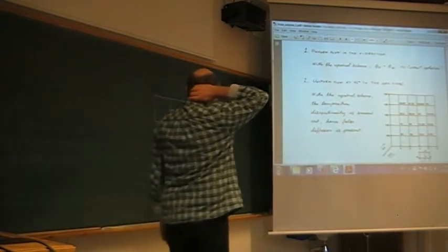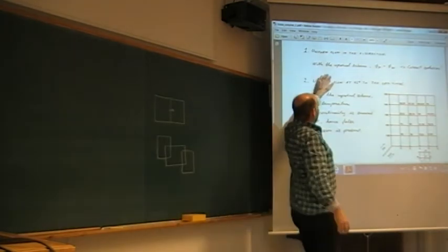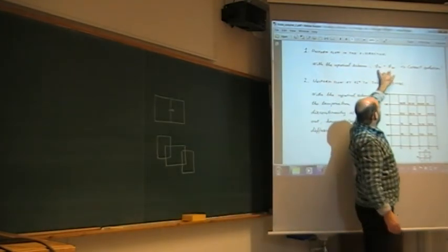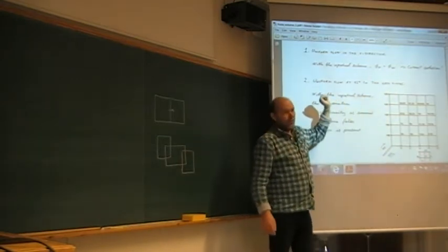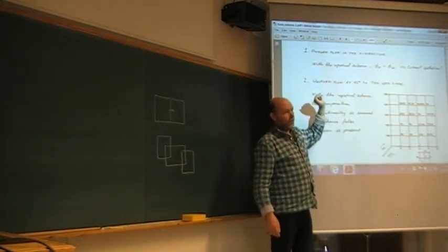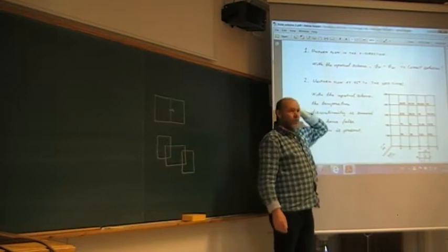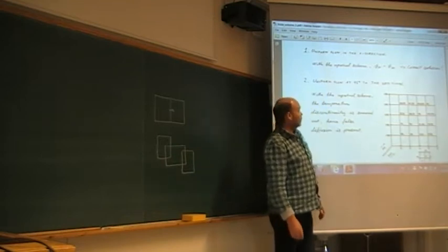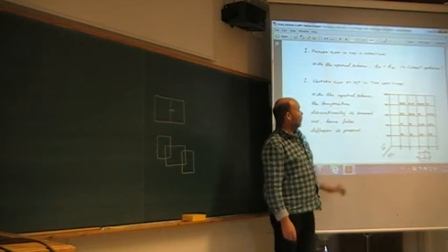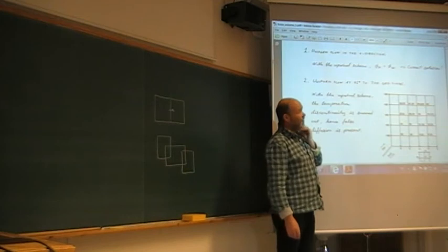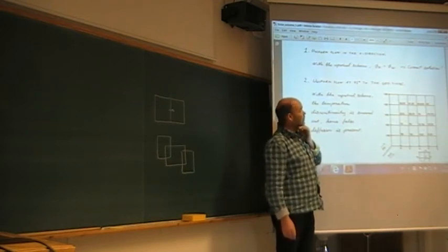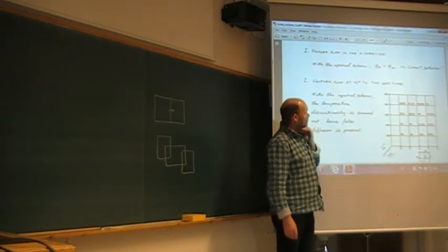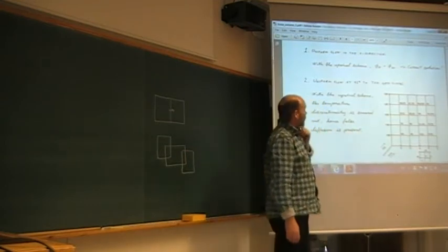Now for the first order upwind scheme, you will have the correct solution directly. With central scheme, you can forget it. You can't use central scheme with the Euler codes. Then it blows up, as we have seen. So only the advection equation there, it's unconditionally unstable. So then, well, it's possible, but then you have to treat it quite special. We'll see as an example later.